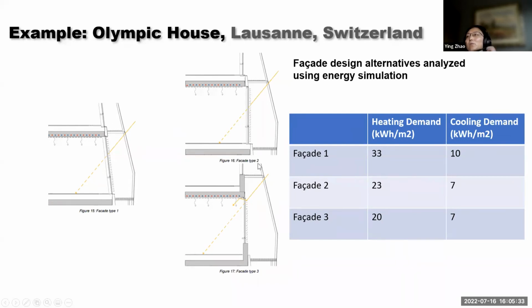Type 2 is vertical, with a similar position of the shade overhang. And type 3 is what they finally used. They have a partial window in the inside layer that reduces heat gain, but they maximize daylight by pushing the overhang above. So you can see a greater area inside the space that uses the daylight.